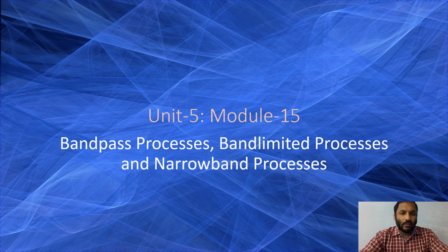Similarly, we will also discuss another type of band limited process. A narrowband process is a band limited process for which the central frequency, the modulating frequency or the central frequency of the band omega naught, is very much larger than the bandwidth. Okay, so as we go, I will show you some pictures, and we will discuss the properties of each of these pictures.